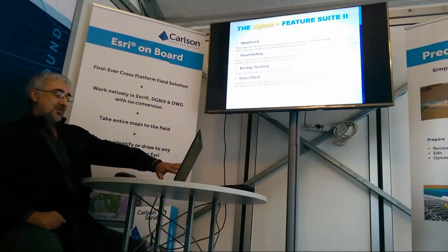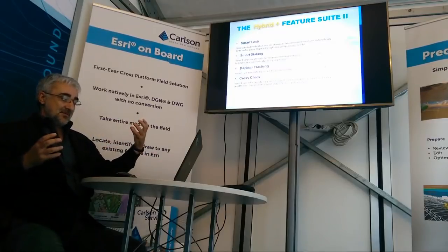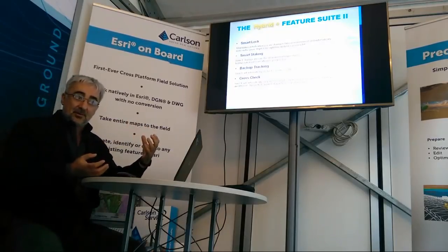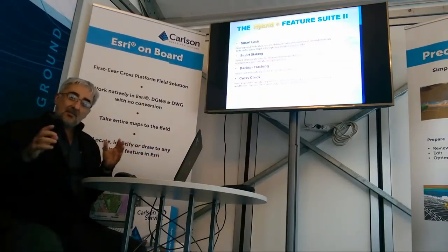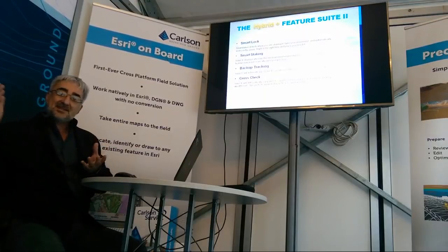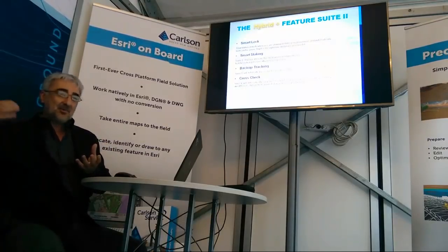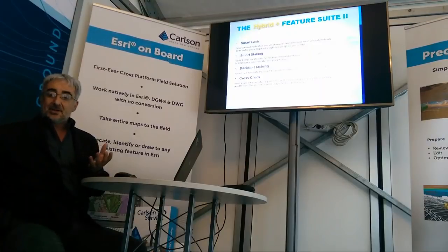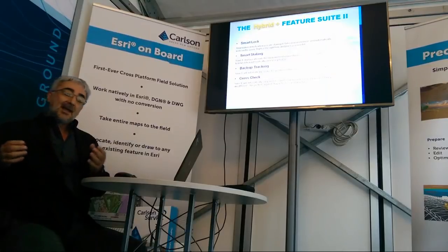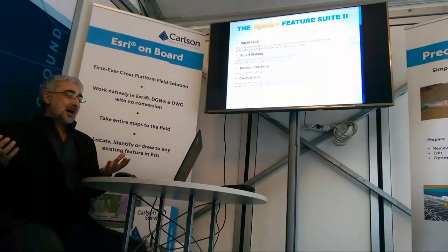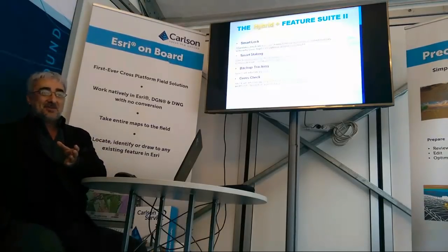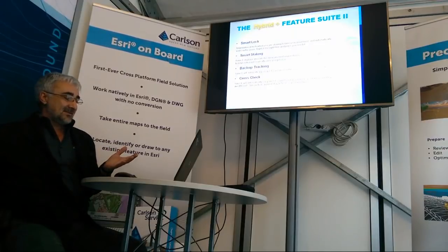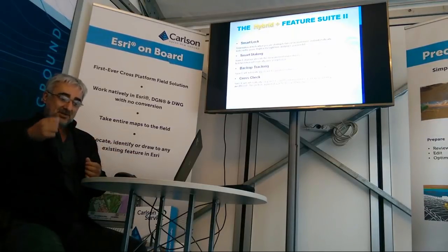Backup tracking, I told you before, if I lose the prism, GPS takes care of the position for navigation. Many people say they don't like the distance meter in robotic working 8 hours a day, because first, it is reducing the time of the batteries, and second, it is somehow stressing the mechanics of the distance meter. So that means service before time. So people like to measure with the distance meter when you need to make the shot.